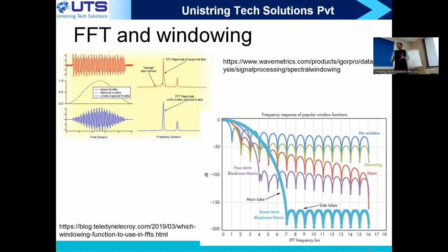But let's assume a hypothetical condition where they are moving with the same velocity, at just adjacent frequencies. I want to detect both of them. Then I need to ensure that the stronger energy is not masking the other. That is what side lobes are about. But the challenge is that when you want such very low-level side lobes, you would mask a substantial number of bins. You understand?